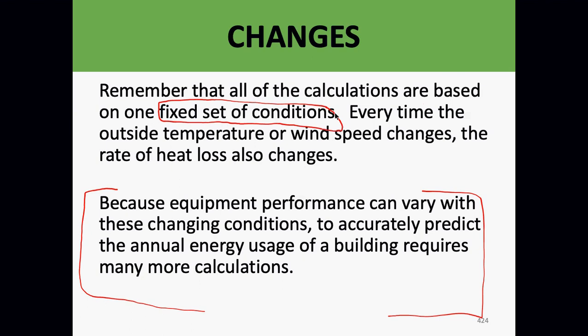I'm not giving you the average for the year round, because your customers are going to be very unhappy if on a 95-degree day, which is sort of a peak temperature day, they're not able to cool their house to 75 degrees. Or even worse, on a winter day, they're not able to keep their house warmer than 65 degrees. Yes, we have one or two days a year that are outside of design conditions, but that is what it is. So, a fixed set of conditions.